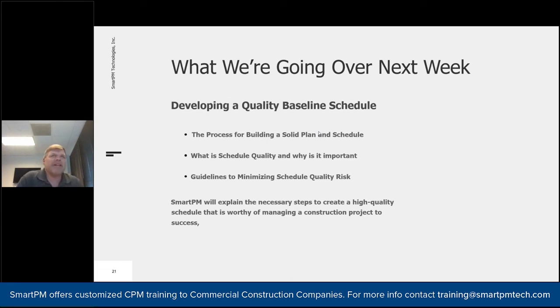That's awesome. But like I said, if you're not following a series of best practices, if you're not understanding what the risks are with certain methodologies of scheduling that aren't very favorable, for instance, having a ton of long activities with like 90-day durations representing entire floors of work is just too much work to actually in your brain calculate progress on, especially if it's, say, an entire floor of interior works, which some cases people do that. Instead of breaking it out per trade and putting order amongst those trades, those things can result in a schedule that's very easy to mismanage, which completely renders the program useless.